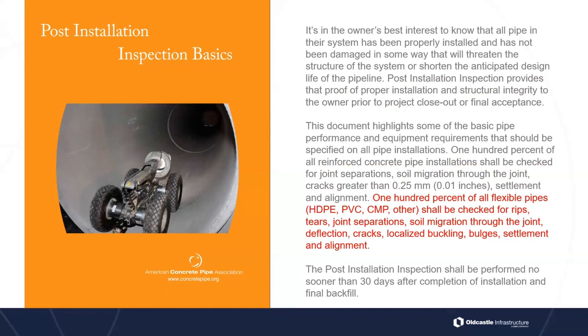So some people say, well, we'll do CCTV to video the concrete pipe, but we don't need to CCTV the flexible pipe because we'll just pull a mandrel through.